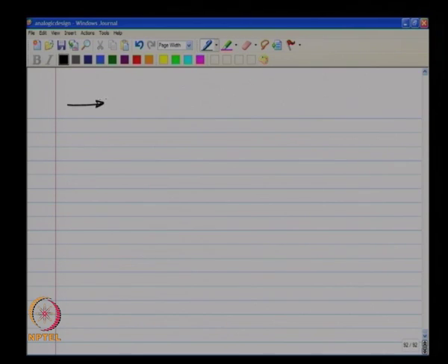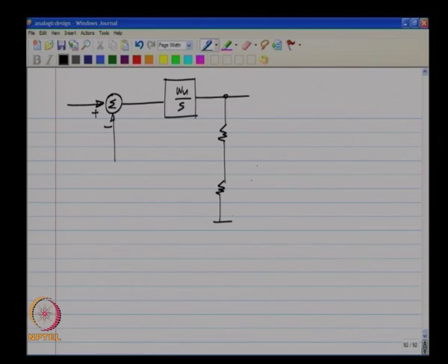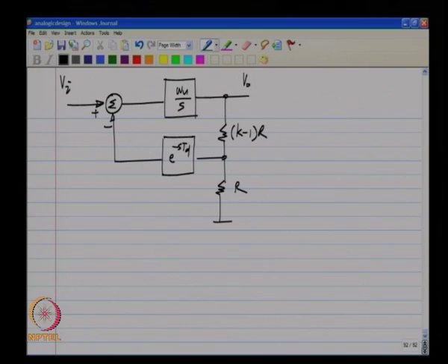So, while modeling the delay, I will use the Laplace transform here. While modeling the delay, what I had done was to insert an ideal delay e raised to minus s times Td. Now, what I have to do is not this ideal delay, but some extra factor that has all kinds of poles and zeros.